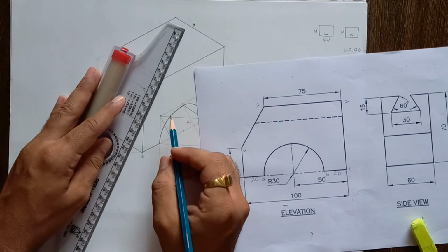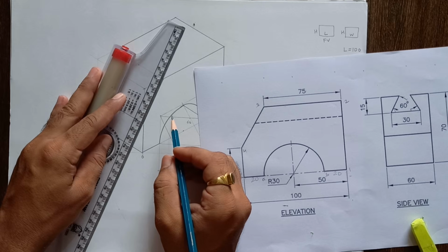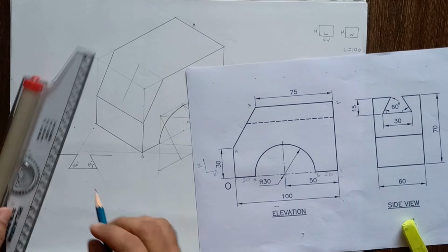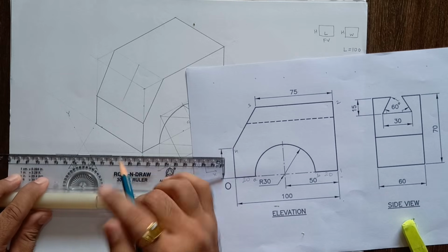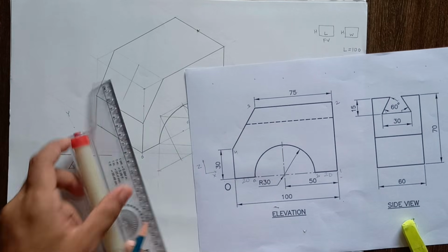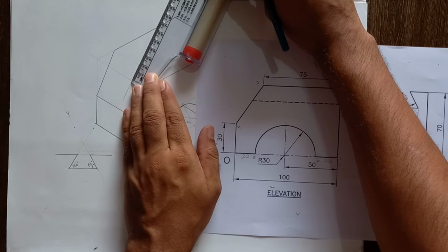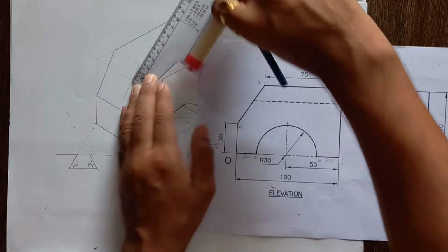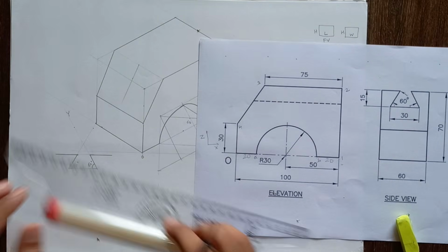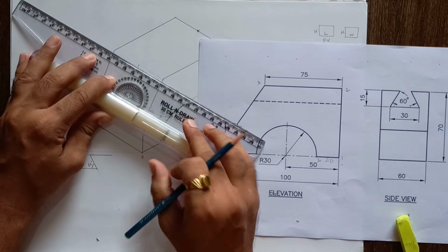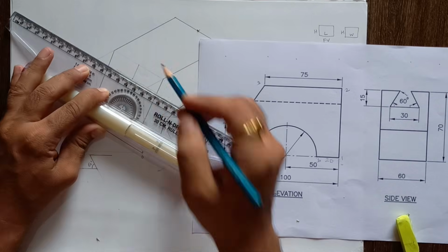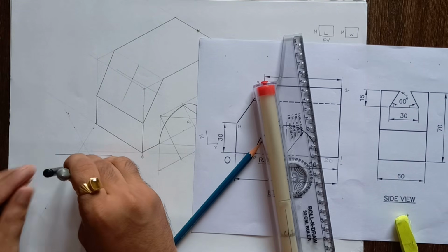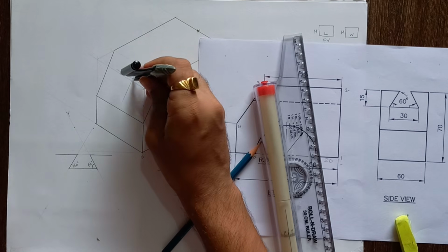So first I draw the line parallel to the non-isometric line. Okay. Now mark 15 mm distance along this non-isometric line, and then adjust a ruler along the width side and draw the 30 mm line. So here measure this distance in the compass. This is 15 mm.